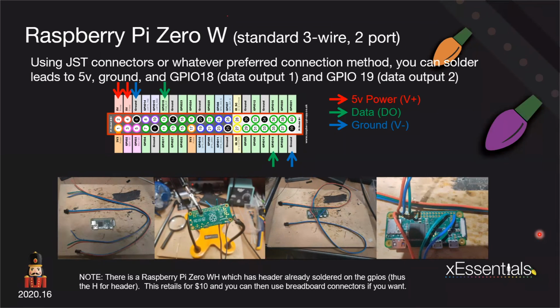Somebody put in the chat, you could put black tape over the pixels you don't want to use. And then in xLights, you may be able to set an individual start channel and tell it not to even light up those pixels. But you're definitely getting into something more advanced to try to figure out.